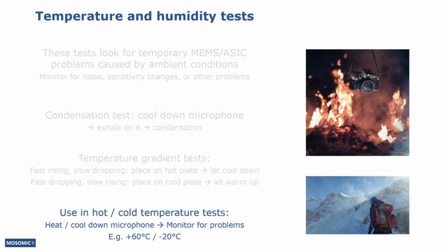In the use in hot temperature test, the microphone is heated, for example up to 60 degrees C, and the output is monitored for problems. In the use in cold temperature test, the microphone is cooled down to, for example, -20 degrees C.